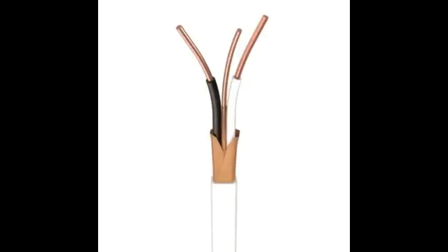For most AC circuits, we want to use solid core wire, often called Romex, after one popular brand name. Use NM cable, which is designed for interior use in dry locations. NM is the most common type of wiring in modern homes. It consists of two or more individual wires wrapped inside a protective plastic sheathing. NM stands for non-metallic, which refers to the flexible, typically thermoplastic sheathing surrounding the cable.